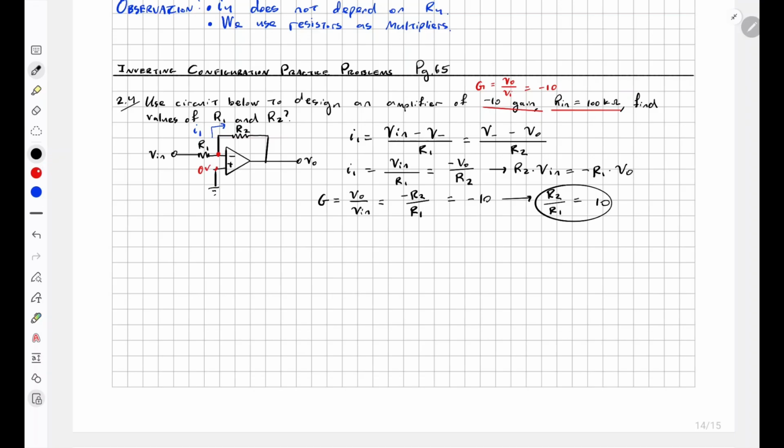It means that if you apply a test signal, which we call Vin, attached here, there are two things we can measure: the voltage here, which is called Vin, and the current that flows in, which we call Iin. Because of Ohm's law, Rin is equal to Vin divided by Iin.